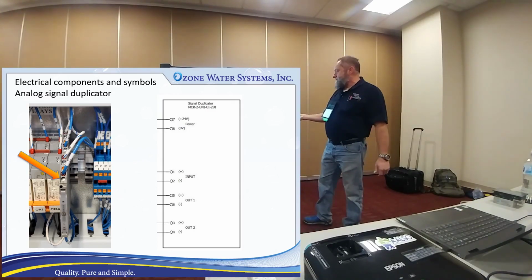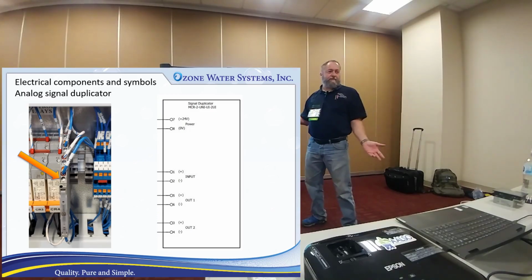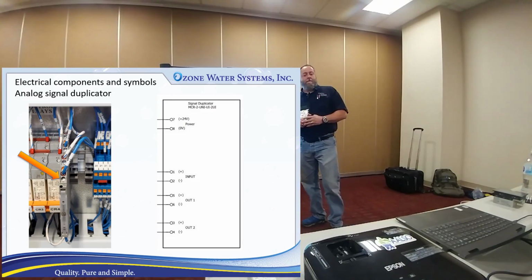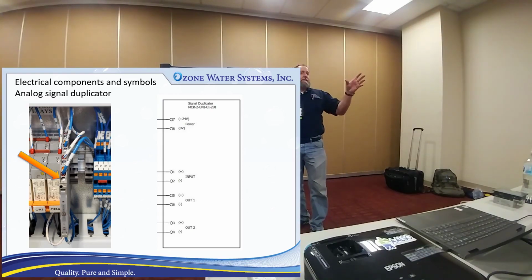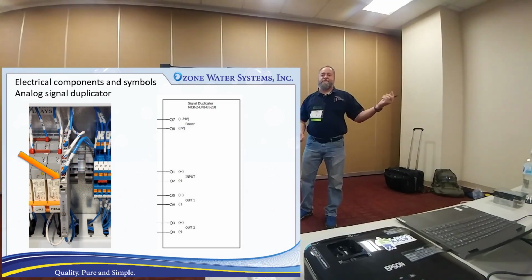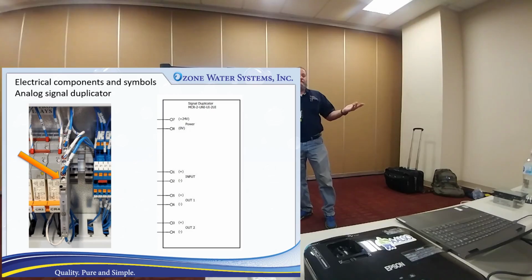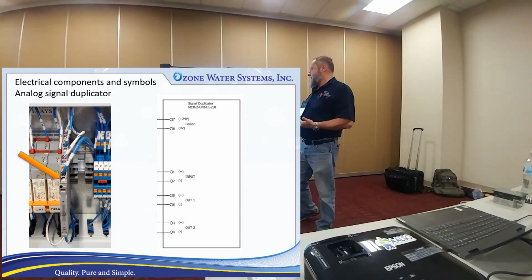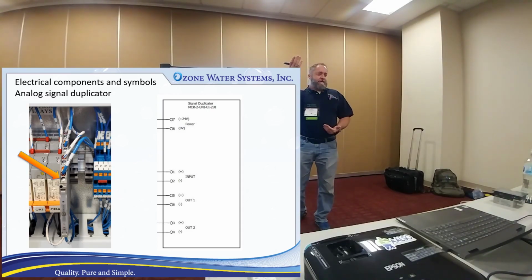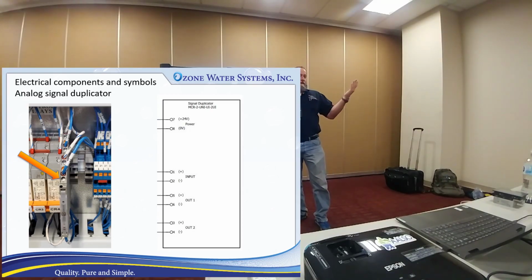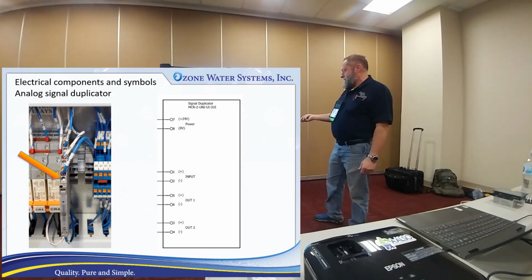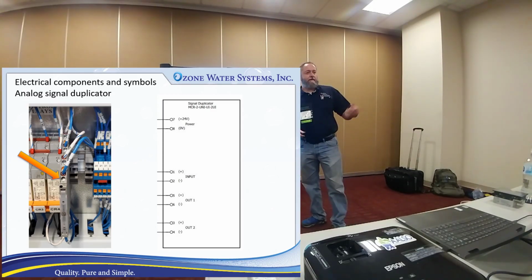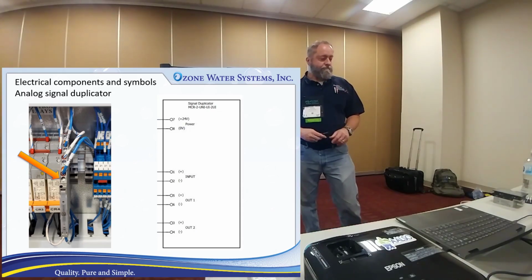Now you can sometimes do that, so you would think that could just eliminate the need. Why do you need a splitter if you can run devices in series? But you can't always run them in series. Like if you've got 2 ozone generators, if they were both on all the time, you could get away with running them in series. But if you need to service one and you turn that generator off, now you've broken your loop and now the other one's not going to work. So in some scenarios like this one, we're always going to have the telemetry system on when that generator's on. So that one makes sense. You can have those tied together in series. This one isn't generally used unless the customer wants to hook it up to their logger or their ACS system.